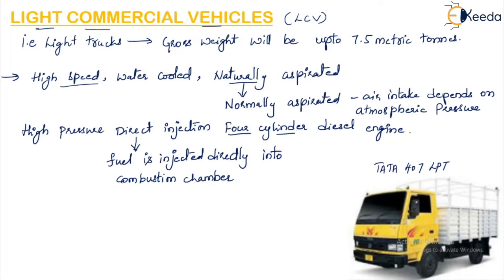Now we will go into the details of the dimensions. Bore and stroke. I have already discussed bore and stroke in our previous slides. Bore is nothing but the diameter of the cylinder and stroke is the distance travelled by the piston inside the cylinder. Bore and stroke of this truck, Tata 407 LPT, is 97 and 100 mm respectively.